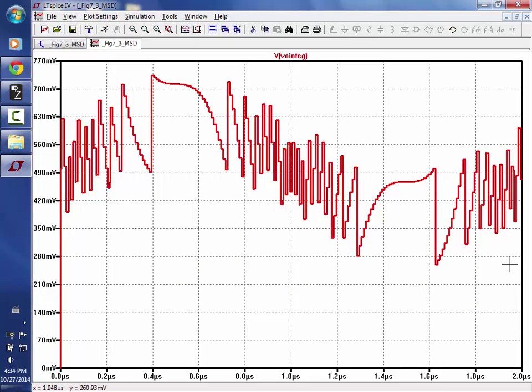Now we'll derive equations for how to govern that output swing later. But the point is, if you're doing your projects and you look at your integrator and it's going up to 5 volts or even close, or down to ground or even close, your integrator is saturating and you're not going to get good results.